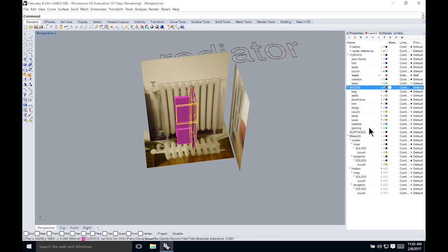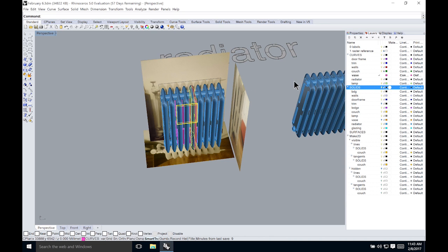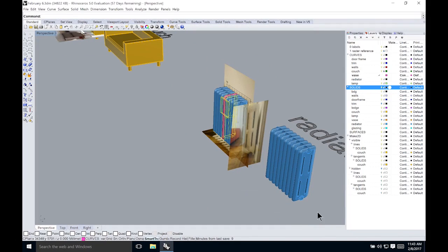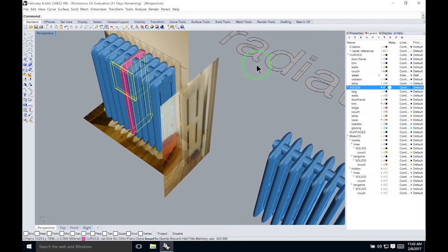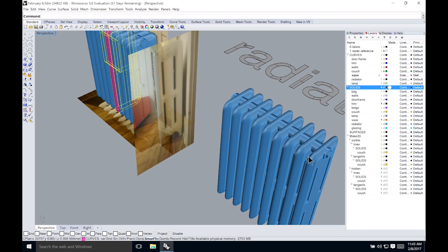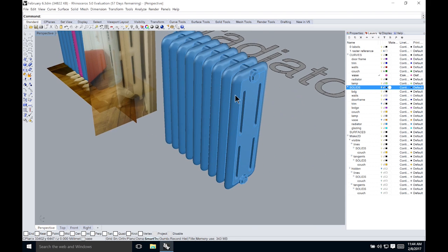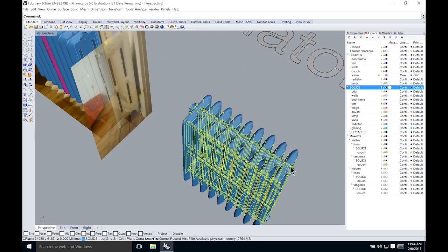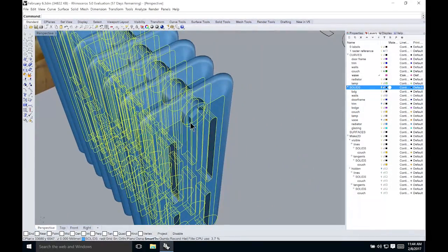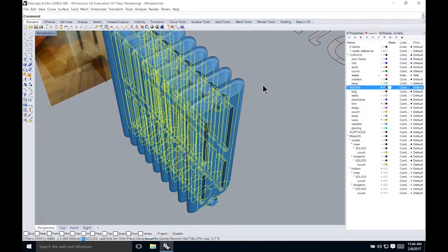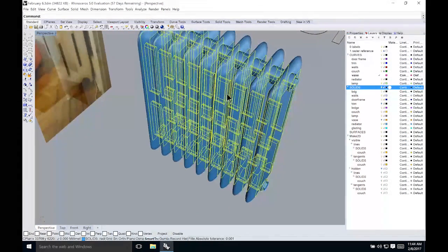And I think finally, to go to this example, I copied them 9 times, and then drew a circle that I extruded through these objects, and then used the Boolean union command that I was showing earlier to basically, I think besides these hexagonal pieces here, make this a single kind of unified object.